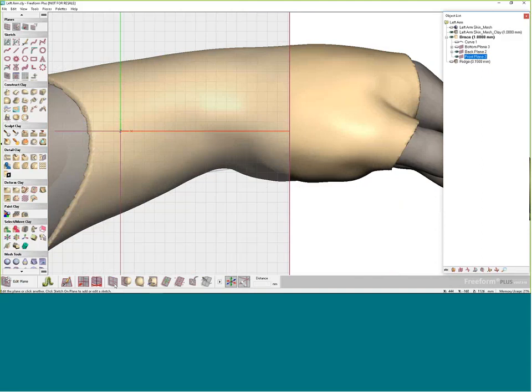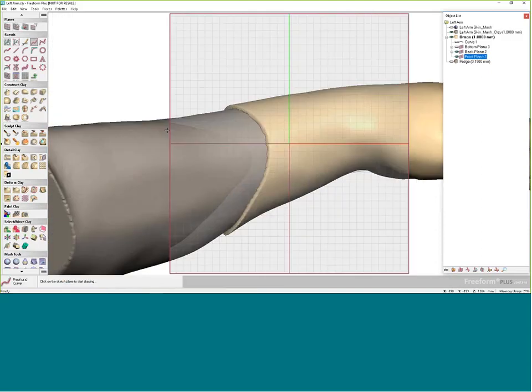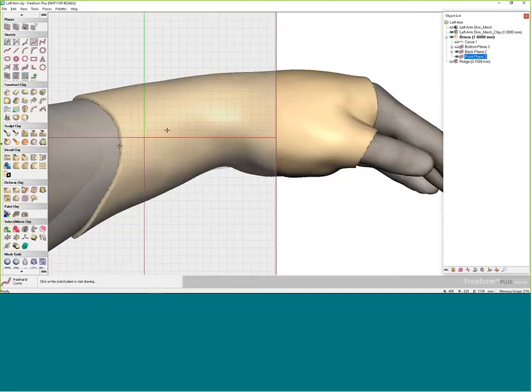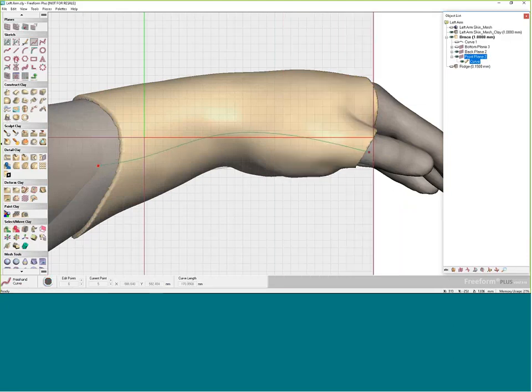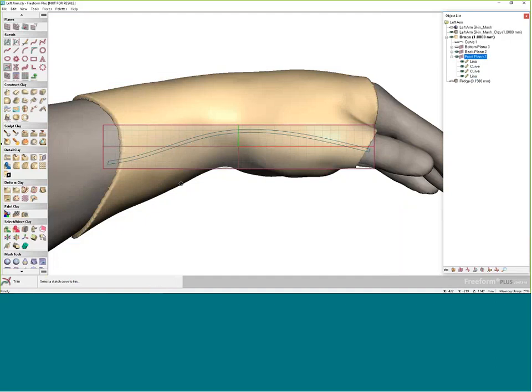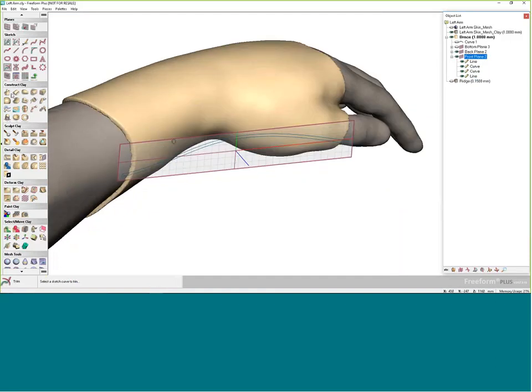Create a plane, put it normal to my view, and then create the curve. And we'll start from here. Looks pretty good. Once again, offsetting this by 2 millimeters. And instead of closing the box, I'm just going to draw a couple lines. Maybe I'll close it on this side. It's pretty tight. And I'll use the trim tool to trim up my sketch and then shrink up my plane.